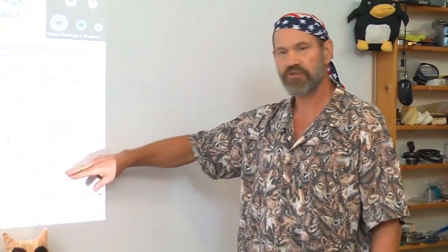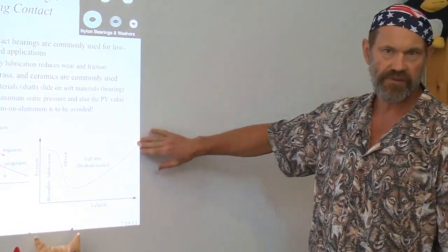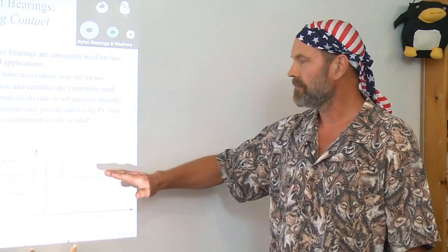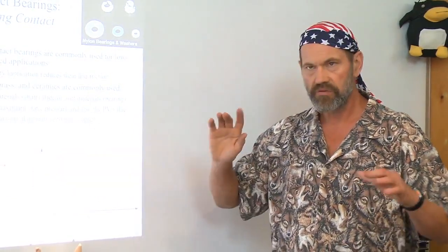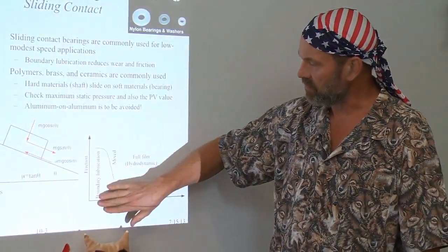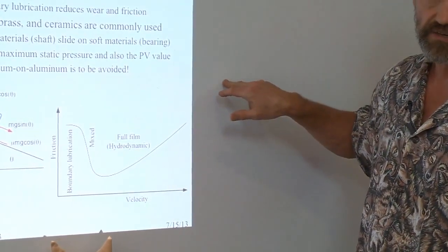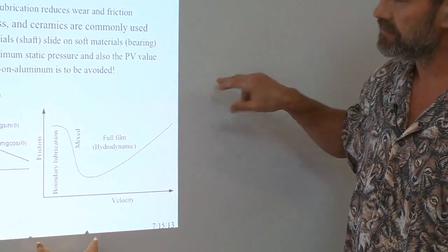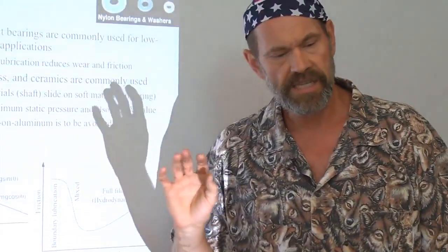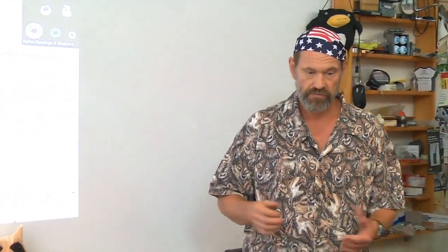You keep running faster speeds and the apparent friction goes up, and what is happening is then you're shearing the fluid and now you're getting more hydrodynamic drag. How is that related to, quote, coefficient of friction? That really should have nothing to do with the applied load. The applied load causing a classic Coulomb type friction really comes in more on the boundary layer. But remember, this just tells you that you have a nonlinear friction effect, something to be aware of with all bearings. How in a sliding contact bearing can I start to assess what's appropriate to use?